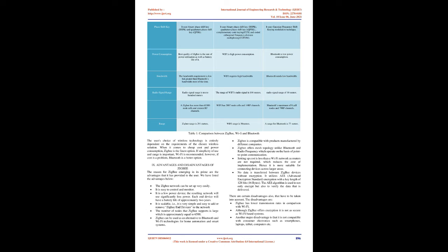Phase shift key. Zigbee uses binary phase shift key, BPSK, and quadrature phase shift key, QPSK. Wi-Fi uses binary phase shift key, BPSK, quadrature phase shift key, QPSK, complementary code keying, CCK, and coded orthogonal frequency division multiplexing, COFDM. Bluetooth uses Gaussian frequency shift keying modulation technique.